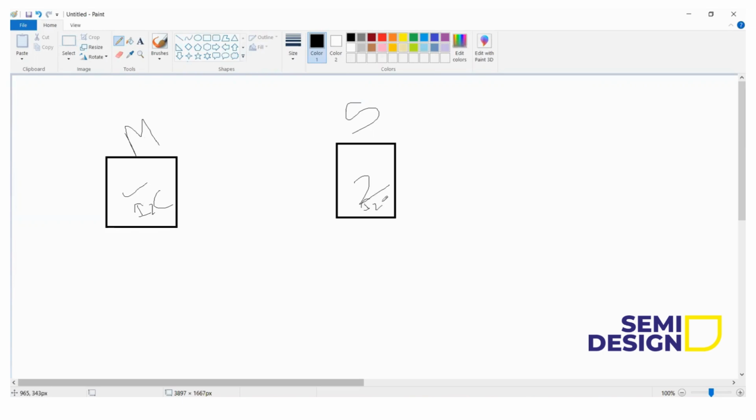You are going to do the data transfer, not a problem. But you are saying that this master is I2C but the slave is not I2C. Okay, let's say the slave is UART. UART has 4 pins, I2C has 2 pins. You cannot directly connect I2C to UART. If it is an I2C master and an I2C slave, each has 2 pins and you can directly connect them. But if it is an I2C master and a UART slave, then you cannot connect them directly.